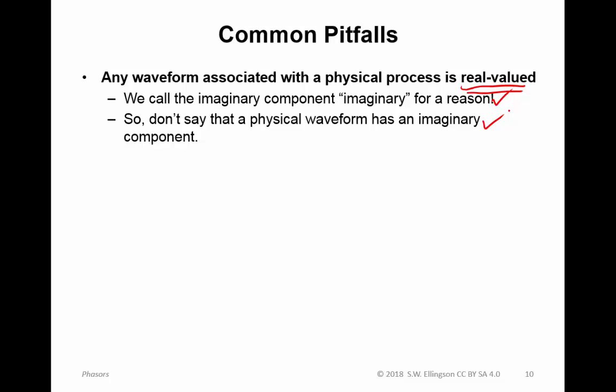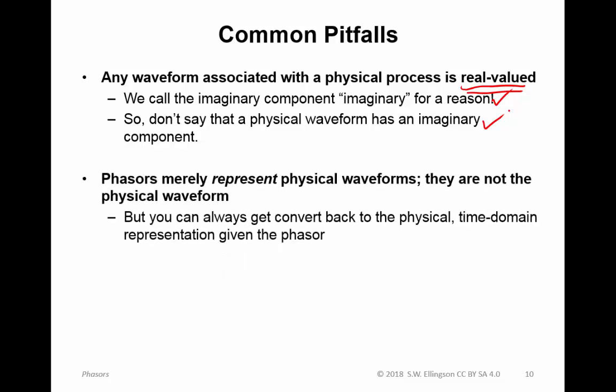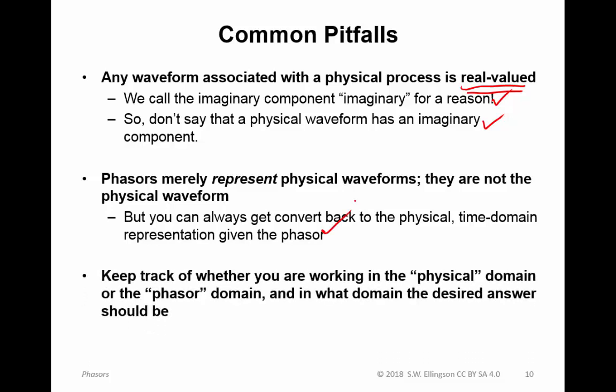Now, all the time we leave answers in phasor form. But again, that doesn't mean that that phasor is the physical thing. It is, again, simply a representation of the physical thing, usually a sinusoid. Phasors merely represent physical waveforms and are not the physical waveform. But you can always get back to the physical time domain waveform given the phasor. Always keep track of whether you are working in the physical domain or the phasor domain, and in what domain the desired answer should be.